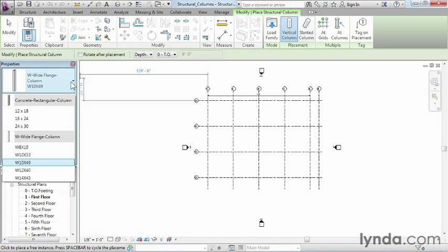Unfortunately, this building is a great big building, so as a result of that, all these structural members that we're looking at right here are pretty small for it. So we need to load in a family that's going to be the appropriate size. To do that, over here we see that there's a big button that says Load Family. Go ahead and select on that.